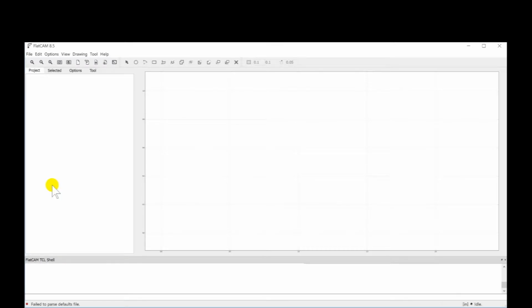After designing your board in Eagle, Altium, Fritzing, Multisim, or your favorite Gerber-compatible CAD program, export Gerber files for the top and bottom traces and an Excellon file with your through-hole data. Before exporting, make sure your designs are above and to the right of the origin in your CAD program. We recommend you use a copper board at least a ½ inch wider and longer than the board you are printing. Next, we open the Flatcam software where we will create our print files.